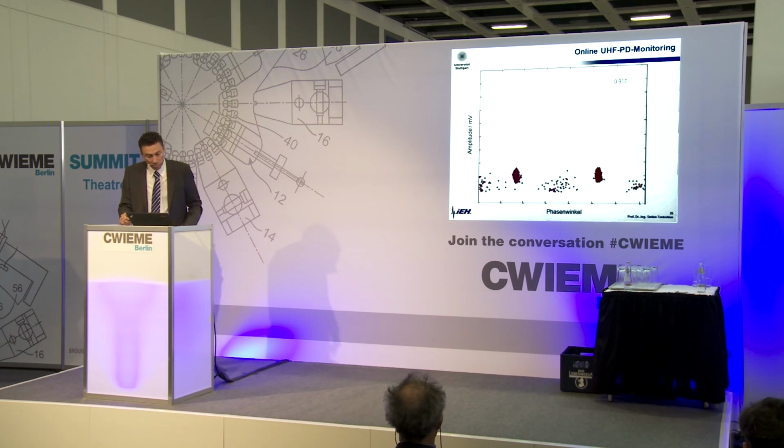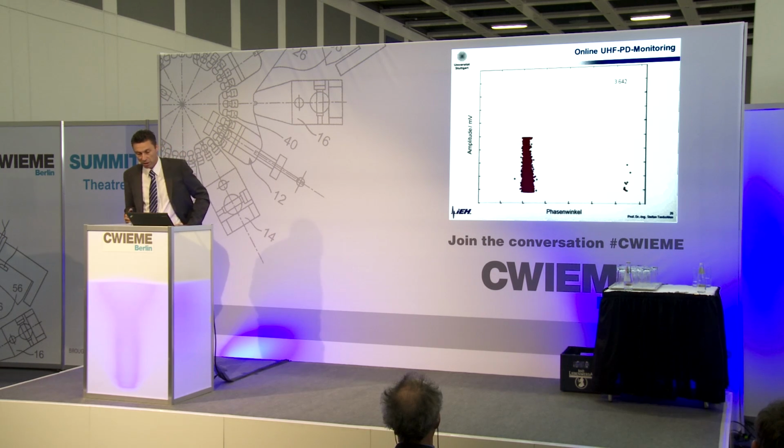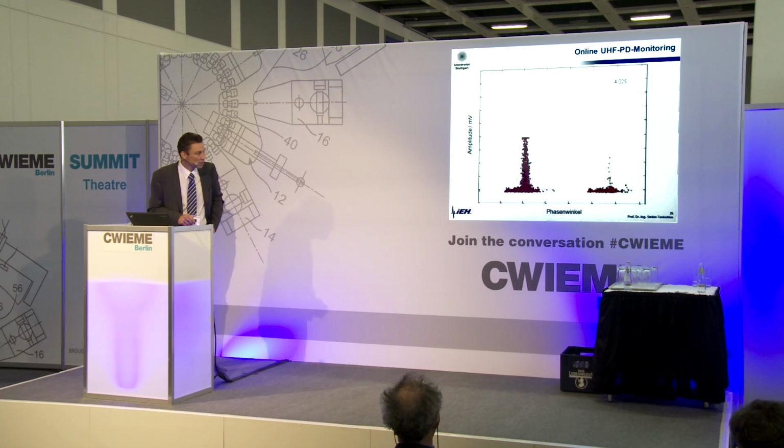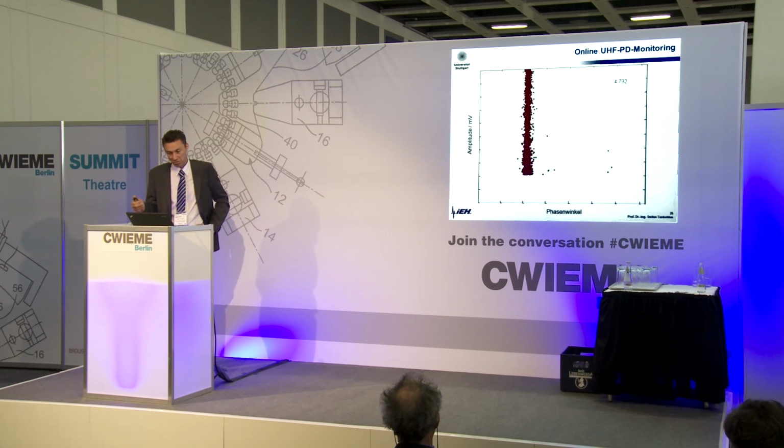This was an on-site measurement, but it was not on-site monitoring. Here in this figure, I show you the result of a UHF PD monitoring system. So for a longer time interval, the PRPD patterns are stored, and you can see that these PRPD patterns are changing quite a lot over time. Here 3 days are shown. During the 3 days, you have strong changes in the PRPD pattern. So PD is not a continuous process. PD can also develop. And now the question is, of course, what does this mean?